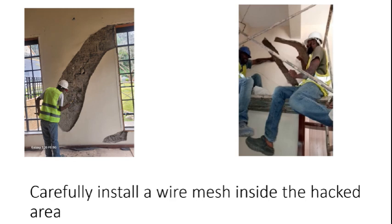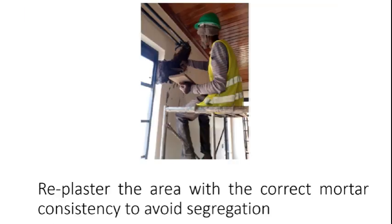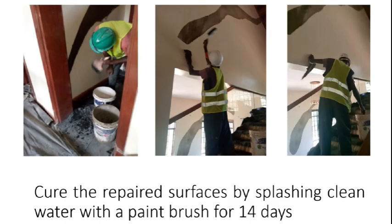You place it neatly around. You continue until it's properly anchored, then replaster the area with the correct mortar consistency to avoid segregation, and then allow the replaced mortar to cure.